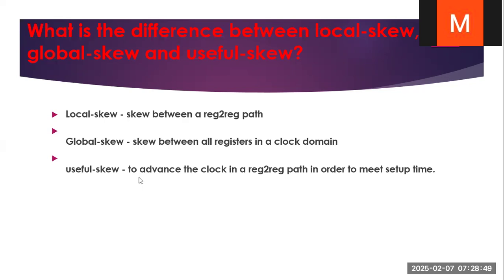And useful skew is to advance the clock in a register to register path in order to meet the setup time. So the useful skew, that is a positive skew, is good for setup.